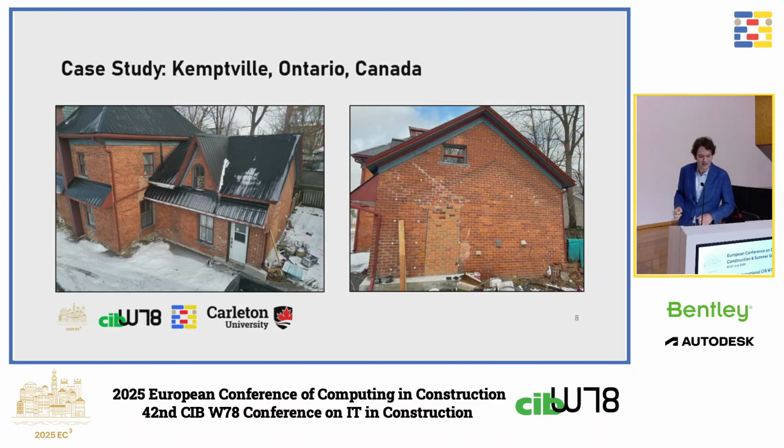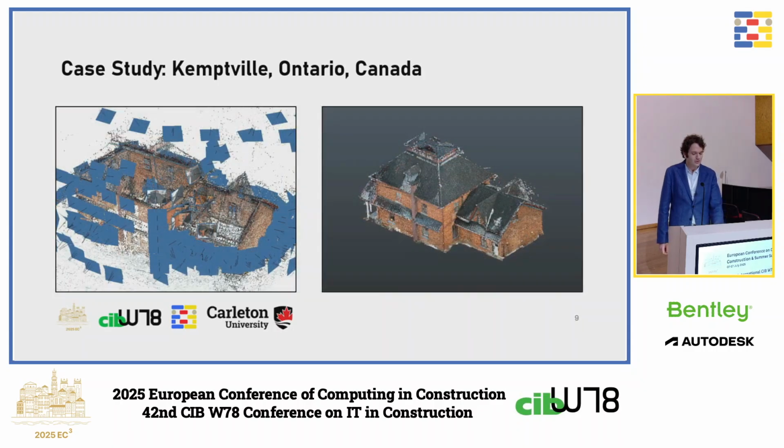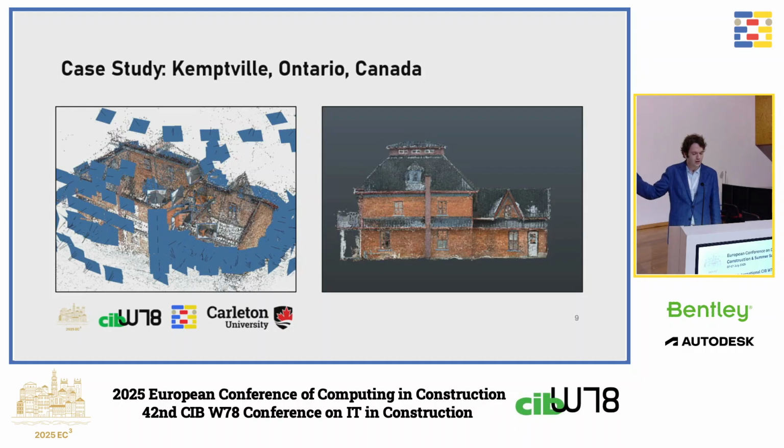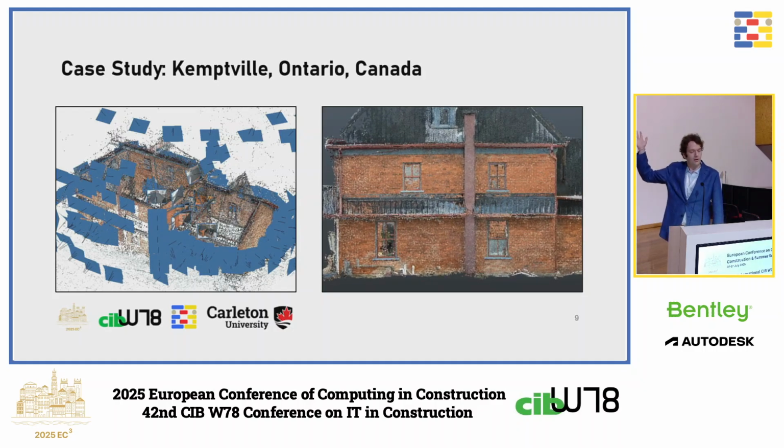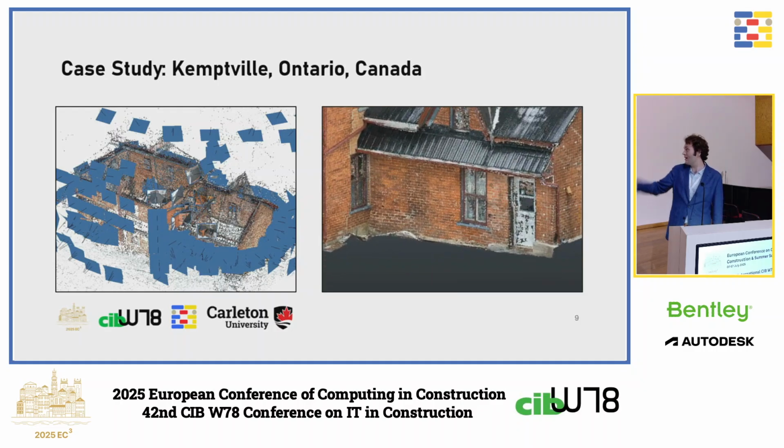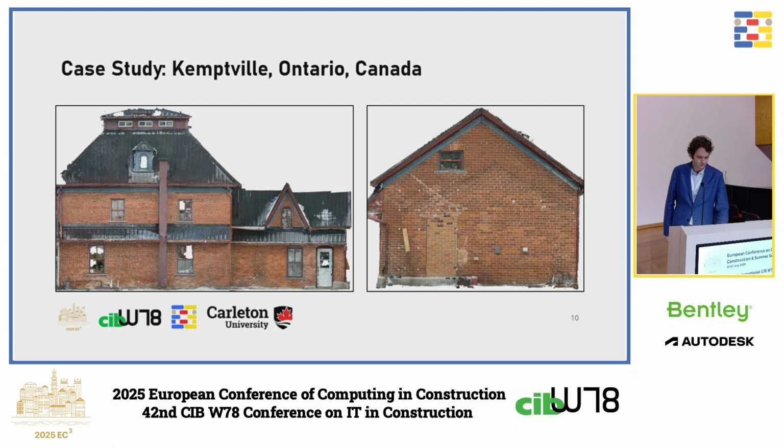Now, as I previously mentioned, I selected this masonry building in my hometown of Kemptville to serve as our case study. To evaluate the accuracy of our YOLO model, I created orthomosaics of two of this building's facades, which provide orthogonally aligned representations of their masonry assemblies. First, I took numerous photographs of the building using both my smartphone and my drone. Then I processed the photos using photogrammetry software, which yielded this sparse cloud, which I then used to generate this dense point cloud, which provides an accurate 3D representation of the building. Then I used the point cloud to generate these two orthomosaics, which are used to evaluate the performance of our YOLO model.